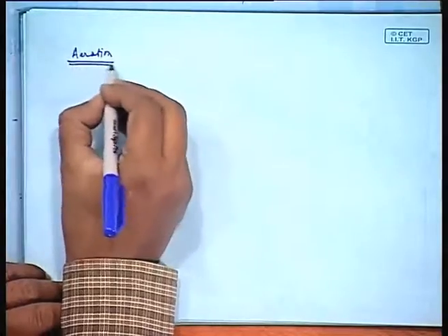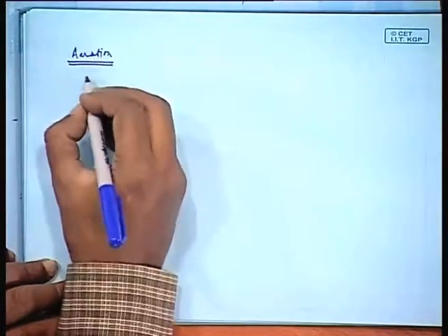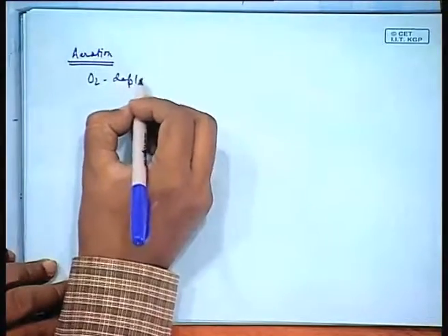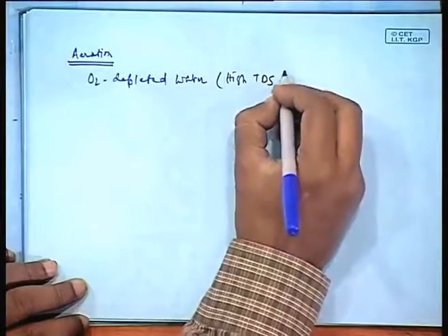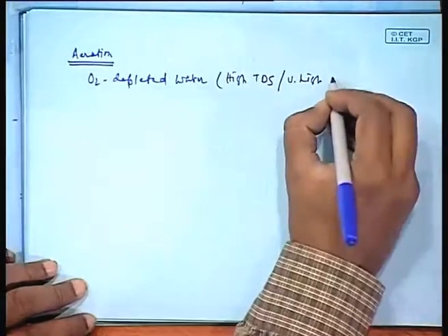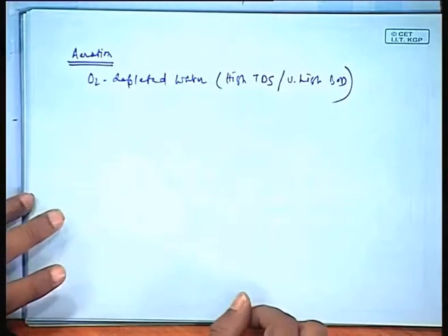In most cases, all these reactions happen particularly in oxygen depleted water. This can result from very high TDS and very high BOD. In both cases, the water may be substantially depleted. You remember the plot I showed you, that with increased salinity, the oxygen concentration decreases. So increased dissolved concentration of equivalent salinity would reduce the level of oxygen in water. Oxygen is also reduced by BOD, biochemical oxygen demand, the oxygen that is used for decomposition of the substances.